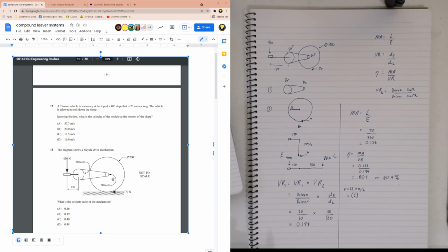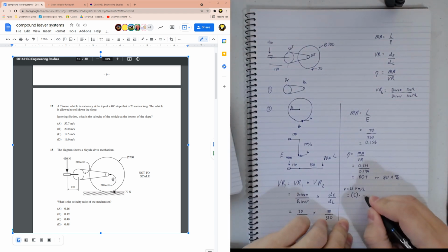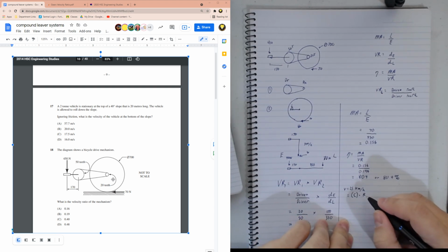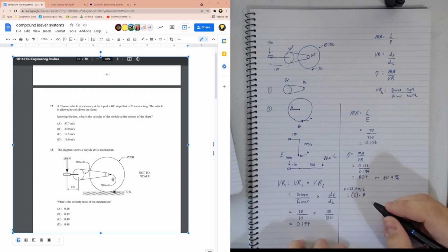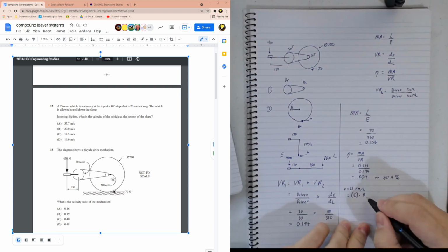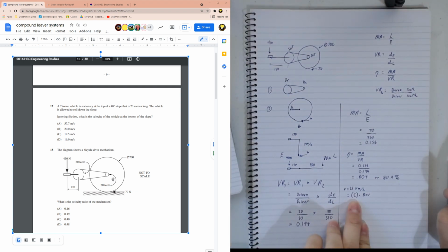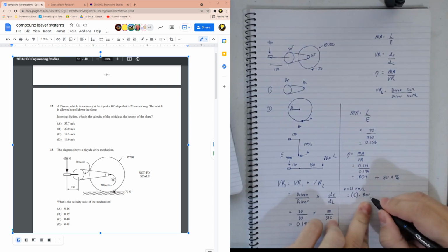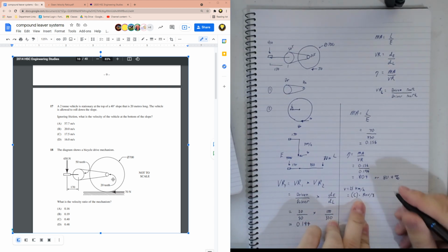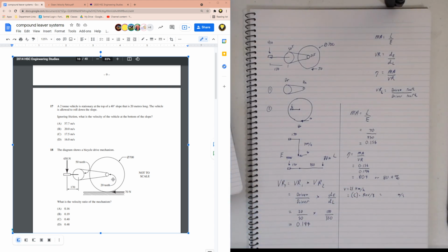So whatever the circumference of our wheel is, times its RPM, revolutions per minute. I'm just going to write revolutions. So if we take our circumference times our revolutions per, let's just say seconds, that's going to give us an answer for how fast we're moving in meters per second. The same goes if we do revolutions per hour, but the point is we are going to be using our circumference. One whole circumference will move our wheel forwards one whole.